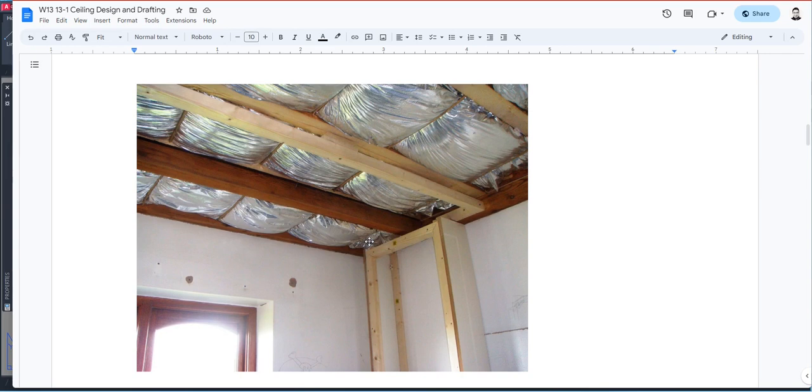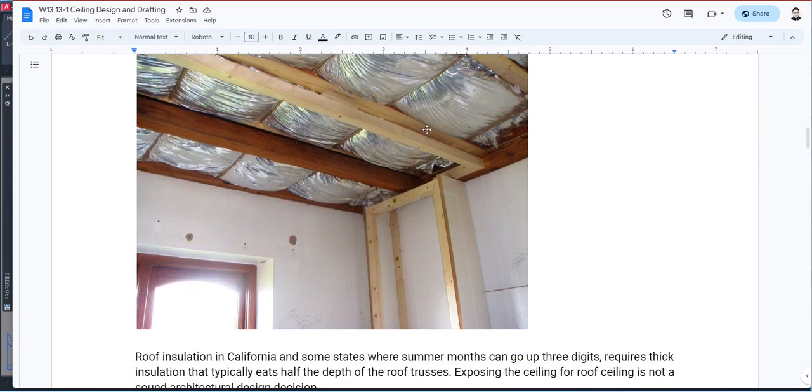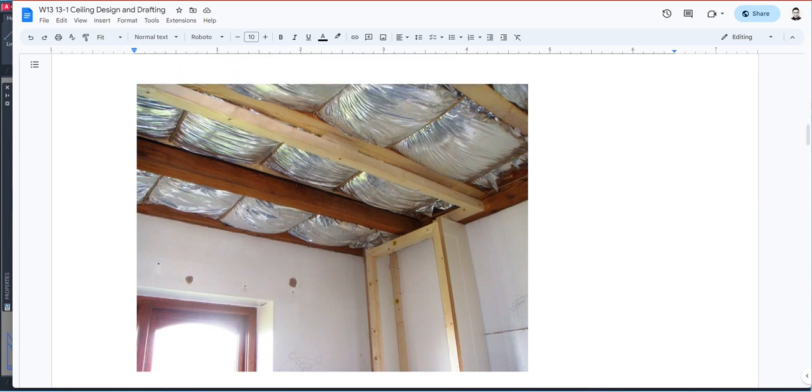receives the sun. Okay, and in California, surfaces that receive a lot of sun tend to be very, very hot during the summer months. So there are a lot of insulation requirements for buildings in California, and because of that there would be an additional insulation on the roof. Walls, you might have an insulation of R16, but on the roof it could be as high as R34. Okay, so when you have this insulation on the ceiling, you don't want to look at this one.